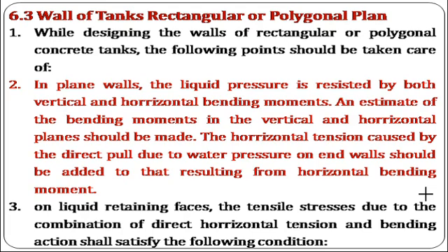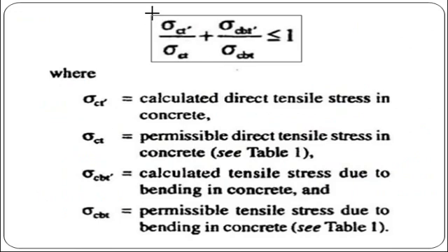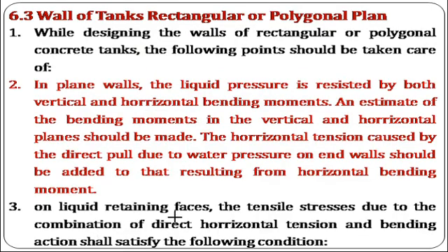Then third point in clause number 6.3, on liquid retaining faces. The tensile stress due to the combined direct horizontal tension and the bending action shall satisfy different conditions. So this is the main condition that should be satisfied: on the liquid retaining face, the tensile stress due to the combined direct, that is combined axial and bending stress, and the tensile stress or tension load,